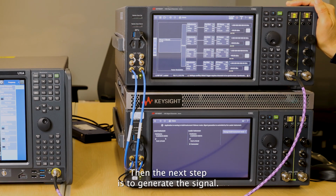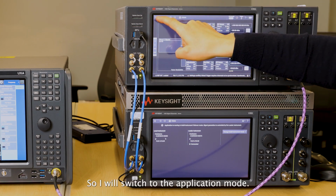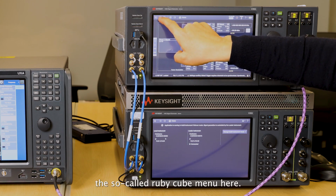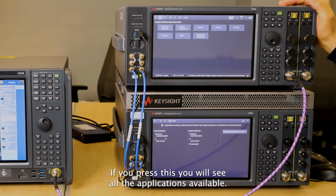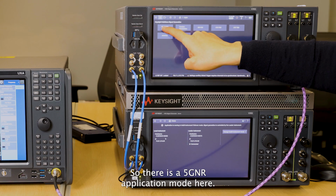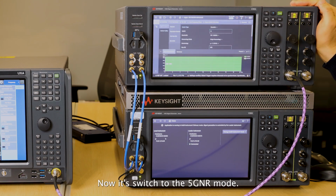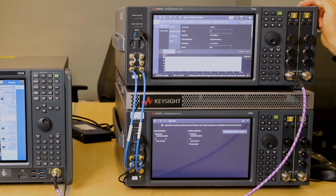Then the next step is to generate the signal. So I want to switch to the application mode. There's the so-called Rubik's Cube menu here. If you press this, you will see all the applications available. There is a 5G NR application mode here, so I just press this button. Now it's switched to the 5G NR mode. And I will switch to uplink.